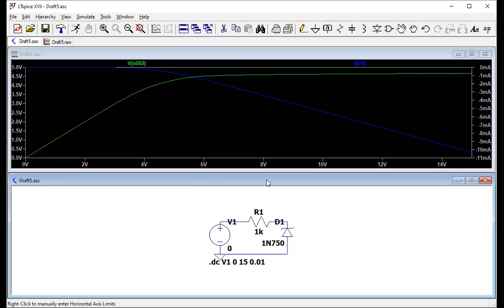And that's going to be actually how we expect to use Zener diodes. They're designed to be used in reverse bias. So that's why we also have a different schematic symbol for them, because these are designed to be used in reverse bias, but normal diodes aren't necessarily. Okay, so that's it for this little look at things in LTspice, seeing how it simulates, and then we'll start talking about Zener and avalanche diodes.